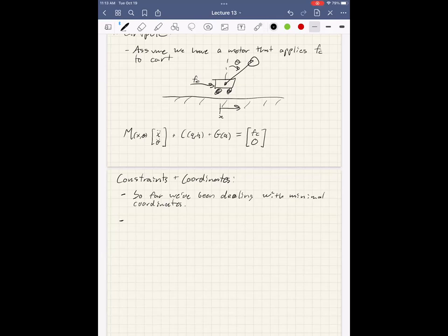In particular, it's usually the right move for fixed base classical robot manipulators where you're stuck to the world frame and you have a bunch of links and joint angles and everything's nicely described in terms of joint angles. That makes tons of sense in that kind of setting. And that's the standard thing. But it can make less sense in a lot of more complex robotic systems that have floating bases, like mobile robots, and that have, in particular, closed loops, which can be very messy to deal with in this way. It becomes ambiguous how to define your coordinates, and there's all kinds of weird stuff that can happen. So think like a 4-bar mechanism like this, those cause problems.